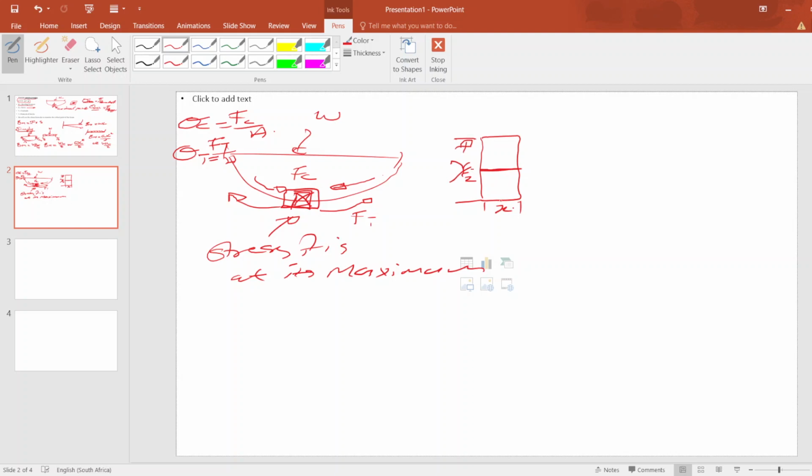Now after we've got the centroid of this beam, we can determine which stress dominates on that critical point. Then we draw the bending stress graph, right? Then we are able to tell which stress is dominating. We said that on the inside, the stress is compression. Outside, it is what? It is tensile. That means the upper part of this beam here is experiencing what? Compression, right? Then the outer part here is experiencing what? Tensile.